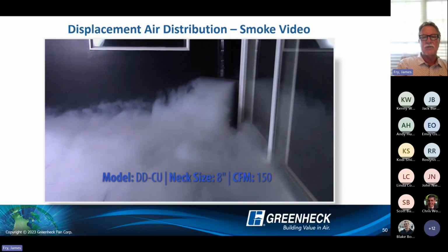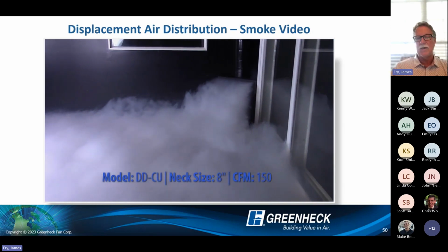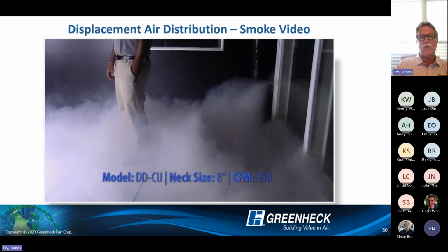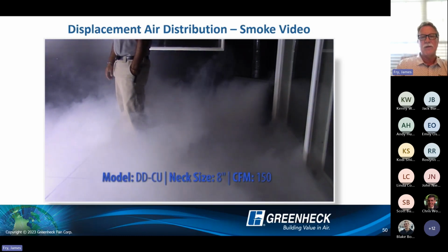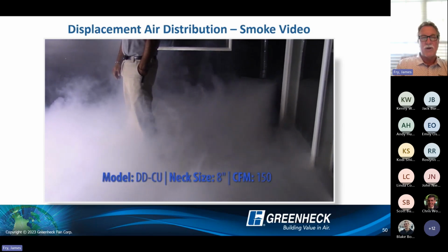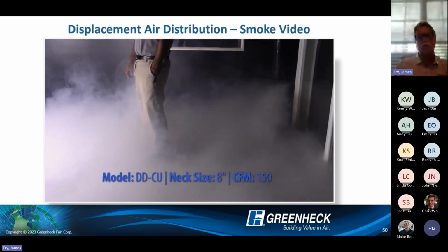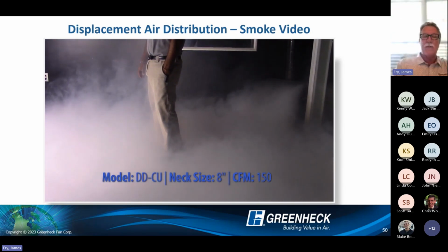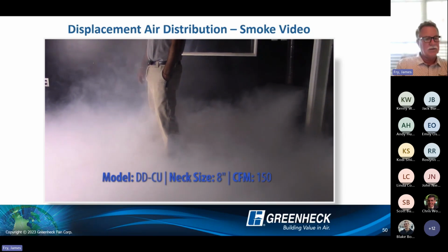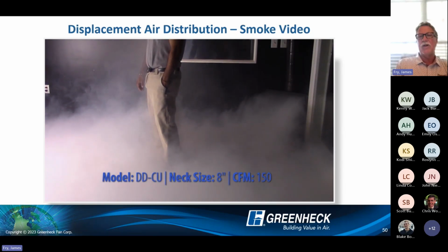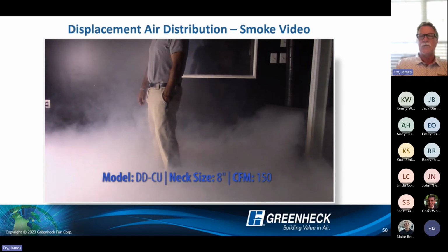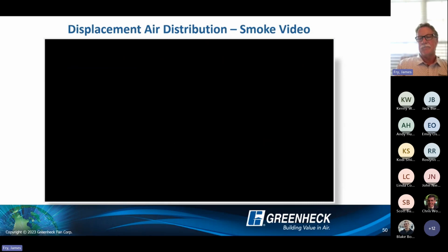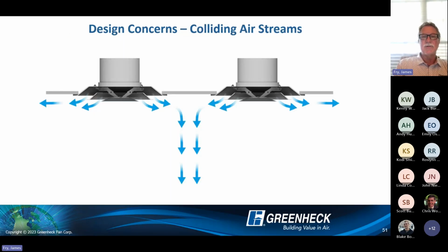So it's going to reach a heat source. Once it reaches that heat source, it will convect up. It'll displace the contaminated or hot air to a higher return. See, as it walks to our lab tech, the air will start to convect up to him. It will do the same thing with computers, electronics, lights, same situation. We're just trying to condition the air in the occupied zone where we are. If you're in an application with a very high ceiling, casino, concert hall, theater, we don't want to condition that air at the ceiling level. We just want to worry about where we're at, saving energy.